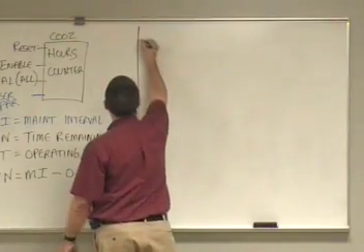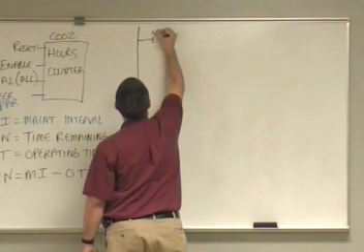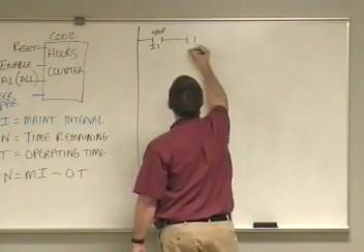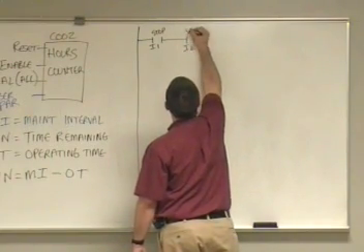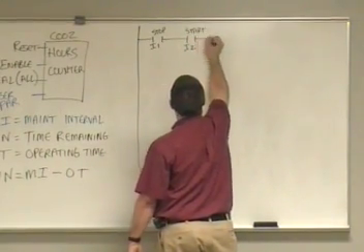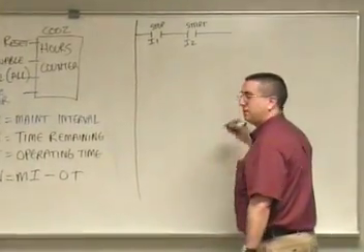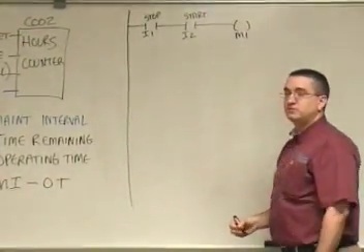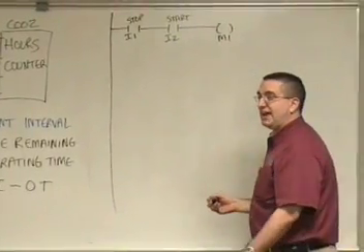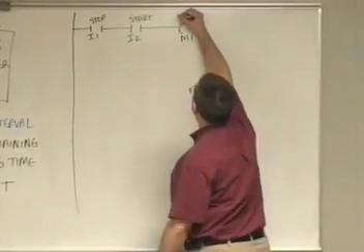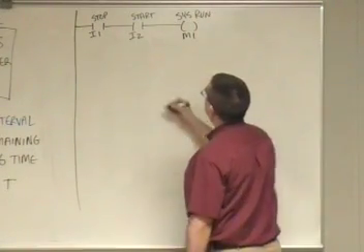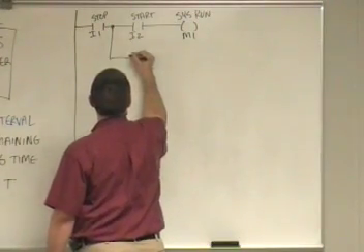Alright, in the hours counter, let's say that we have a system run bit. We have a stop, which might be I1. We have a start, maybe it's I2. I don't know if that's how they're wired on your boards, but that's how I'm going to do them. I have M1. What do I typically use M1 for? Flag. The flag. System run, that's what I like to hear. System run flag, very good. And then down here I have an M1 holding contact.